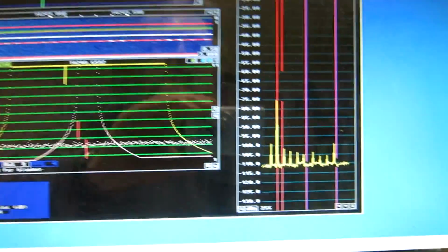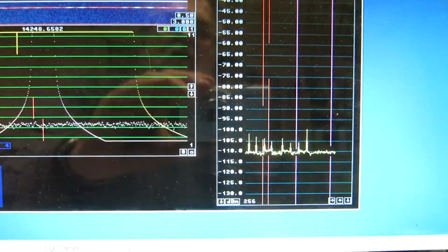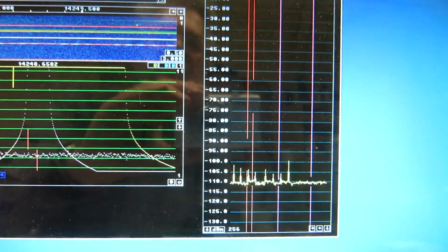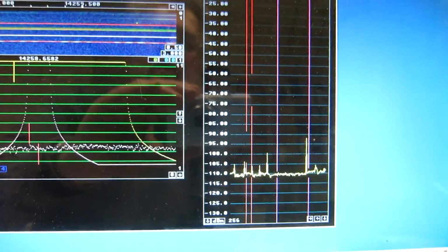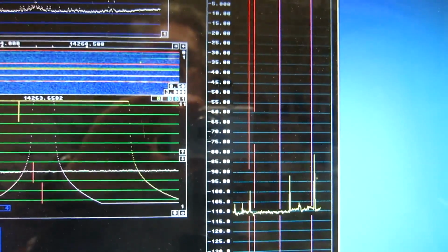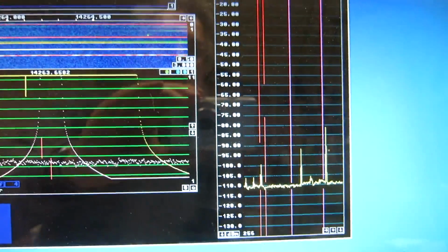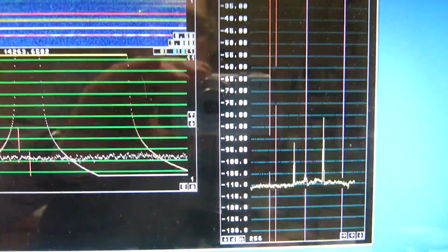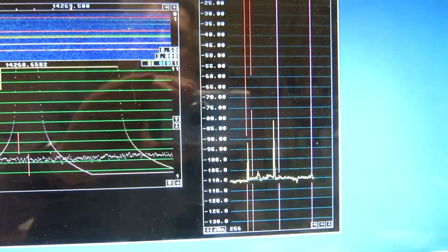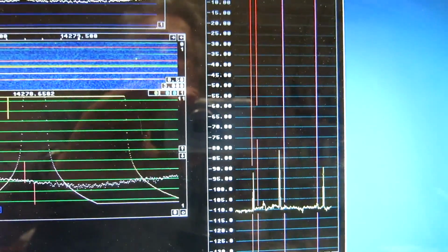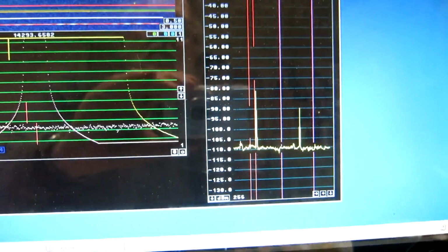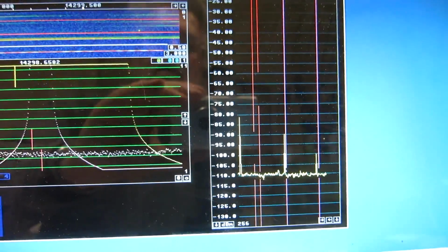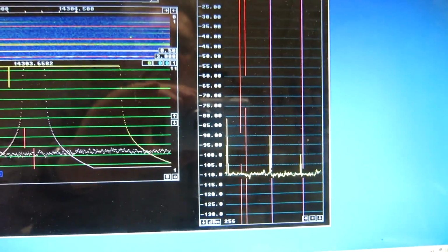It doesn't happen to come right within the 1 kilohertz passband, but a couple of spurs isn't really a problem in SDR, because we could change the LO to not make them interfere with the desired signal. So I don't see any horrible problems.